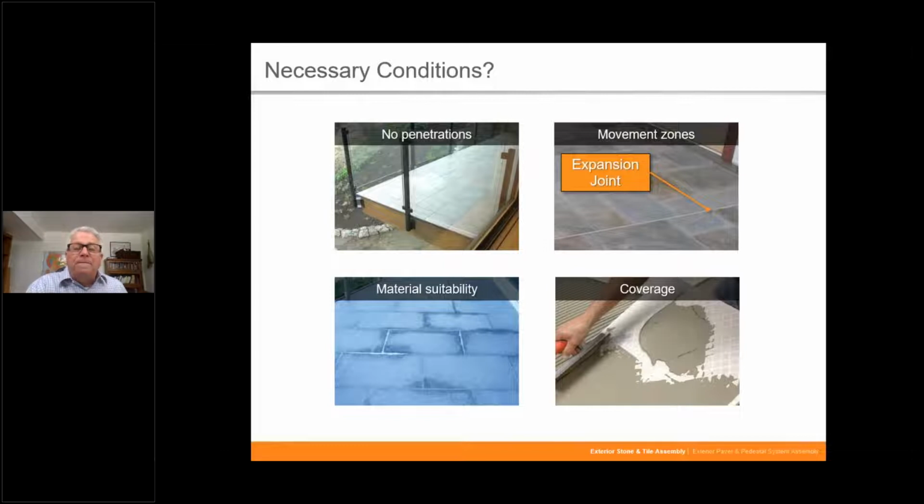How about railing? Now, it's a great practice to not even interrupt the waterproofing with the railing or any sort of penetration. So you can see in this photograph, it would be a great idea to put it in the fascia or even the underside of this balcony that's hanging out if you can.